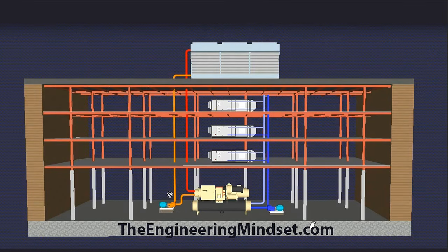And I'm pretty pleased that some of you have spotted that this pump here is actually piped around the wrong way. So this pump should actually be connected to the riser here, or the flow pipe going up to the cooling tower of the condenser water system. Unfortunately, I made a mistake when I was rushing to put this video together, and I piped it onto here, but thank you for pointing that correction out.